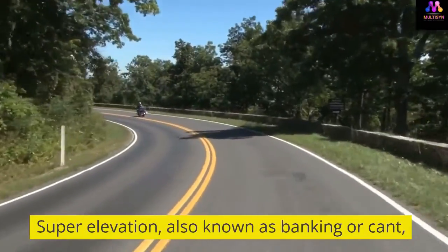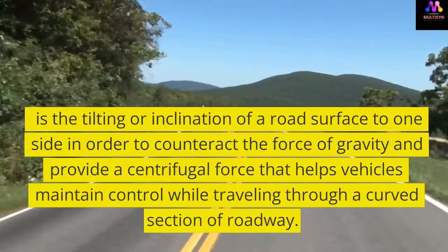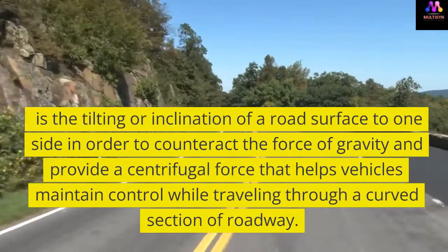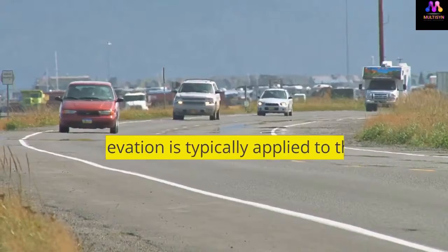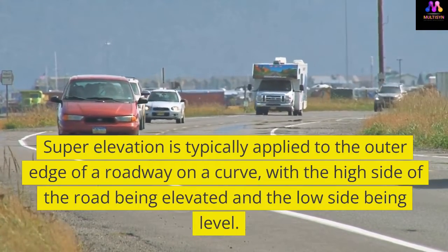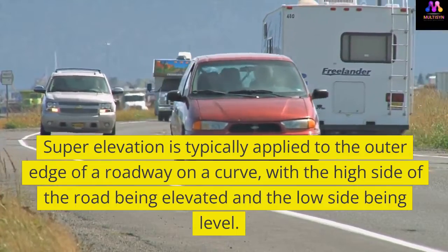Superelevation, also known as banking or cant, is the tilting or inclination of a road surface to one side in order to counteract the force of gravity and provide a centrifugal force that helps vehicles maintain control while traveling through a curved section of roadway. Superelevation is typically applied to the outer edge of a roadway on a curve, with the high side of the road being elevated and the low side being level.